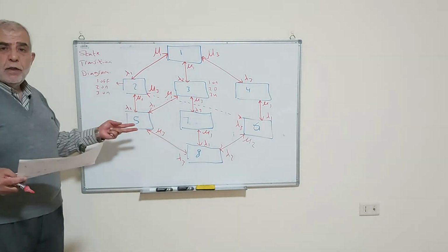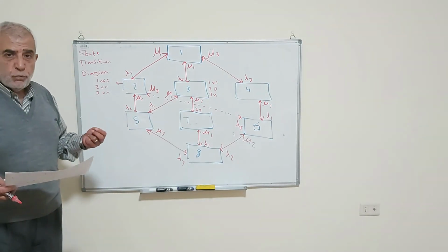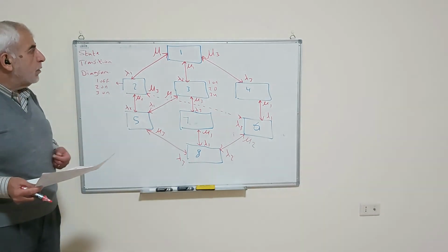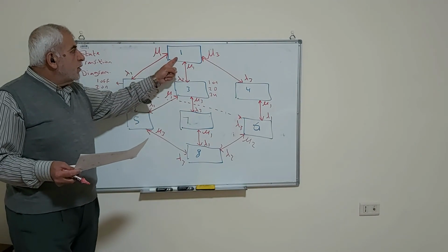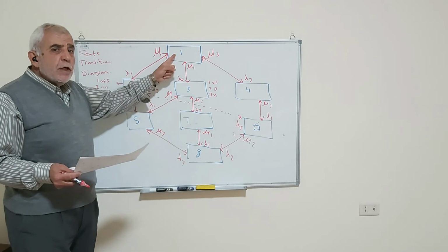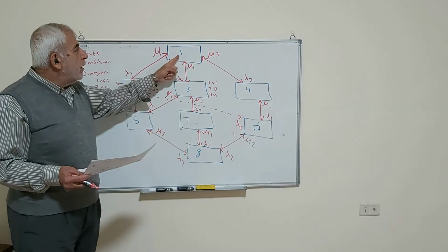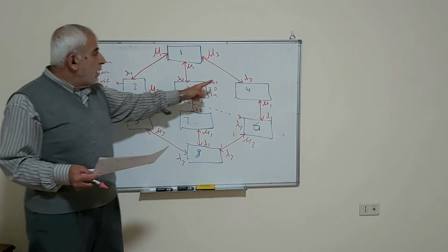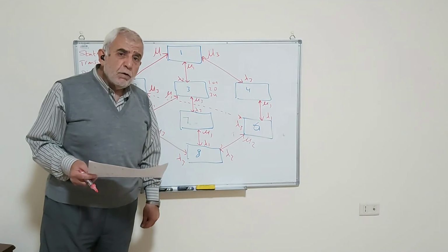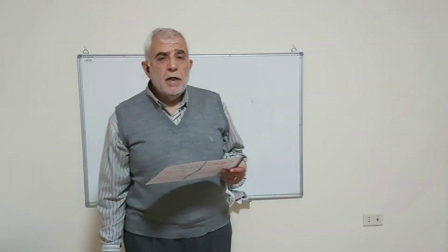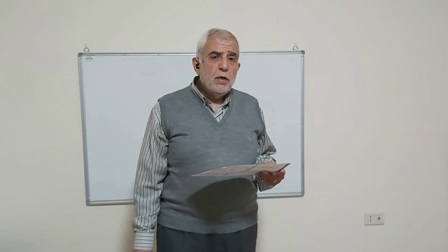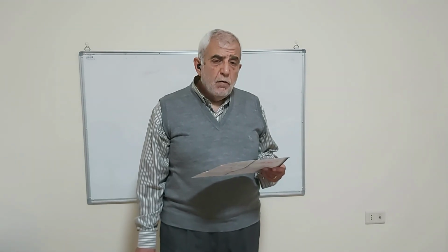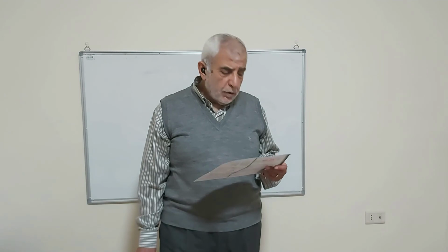Now we are going to evaluate the duration model. It consists of the capacity on, transition rates, and the frequency. For example, the frequency of occurrence of state 1 is equal to the probability of being in state 1 times the sum of the transition rates, which is lambda 1 plus lambda 3. Now we'll carry on to the next slide. Now I'm going to give an illustration, an example, of how to calculate the probability and the frequency of each state. For example, let us consider state number 2.